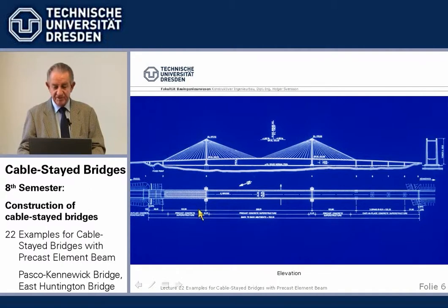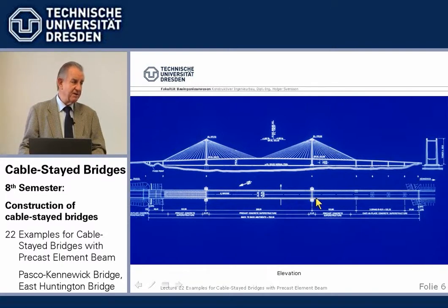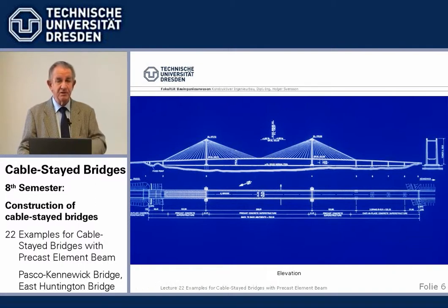The bridge itself, it's hard to read, I know, has a main span of, I say, 300 meters. It was 1,000-something feet, but we designed all that, of course, in feet and inches. But 300 meters is good enough for precast. At that time, it was world record for a concrete cable-stayed bridge by itself. Today, there are, of course, longer spans, but with a heavy precast, I think it's still the record. We have a simple tower with vertical legs and a strut.